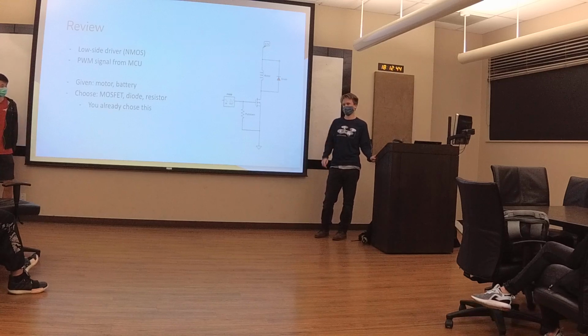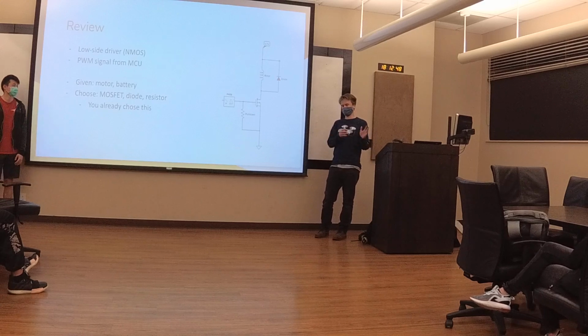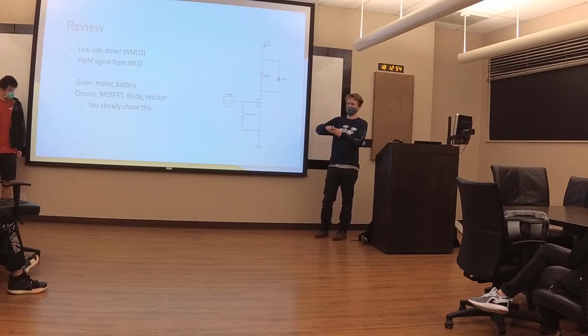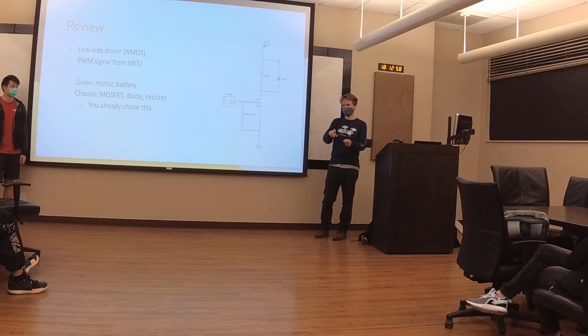Yeah, the inverting level shifter. The bigger problem is that even if we didn't have the inverting level shifter, we don't really have a good way of controlling the PMOS because it's really annoying that you have to pull it high for it to turn off. Whereas with an NMOS, we can just keep it at 0 for it to be off. But yes, you are correct.